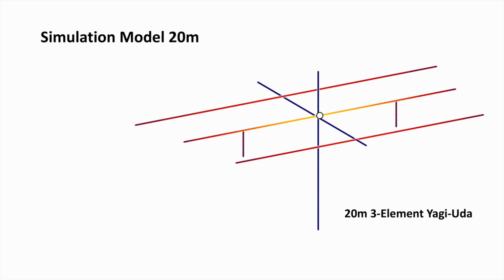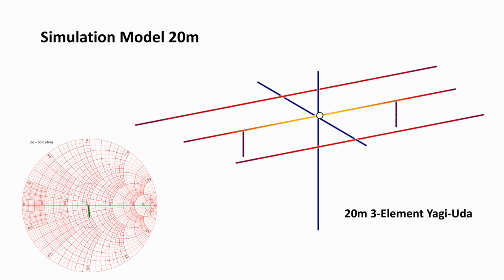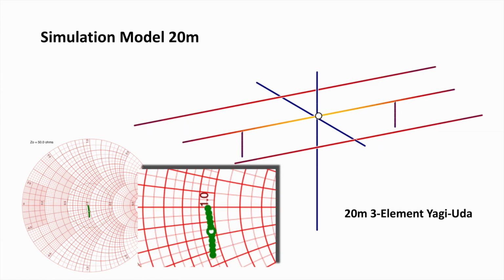When developing the wire grid model for the simulation, I noticed that the impedance of the antenna can be trimmed very well via the length of the director. You can use it to practically reach an ideal antenna matching. In fact, it actually works the same way in reality. I have to say, I like the principle of this antenna with the adjustable elements more and more.